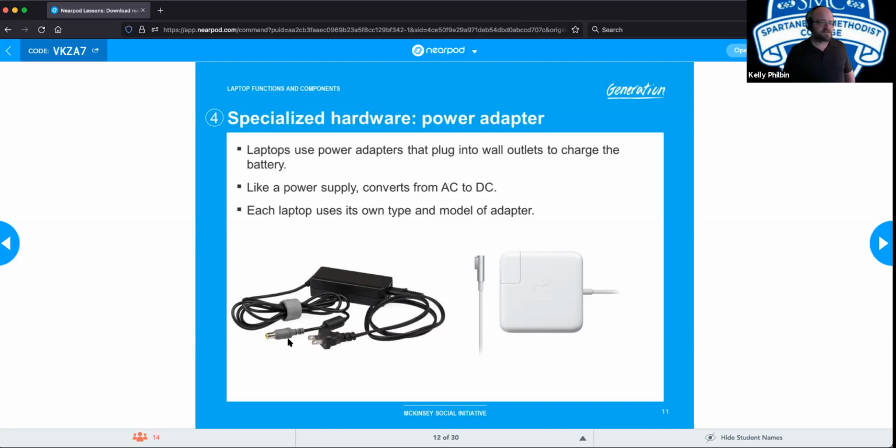What do you mean when you're replacing your plugs, Janina? Is that what you're talking about? Yes. Okay, so if you're replacing your plug, yes, you want to make sure you're getting a plug that is compatible with the electronic you're trying to get that plug for. So if you're buying a plug for a Dell laptop, you want to make sure that the voltages match up. It doesn't necessarily have to be a Dell specific one, but you need to make sure that your voltages and amperages are matching. If your computer only needs 1.5 amps, you need to make sure you're not getting a plug that's providing it with 3, because you can damage your components that way.